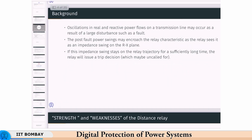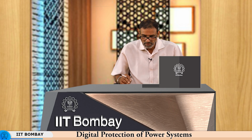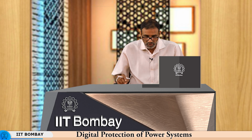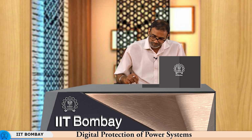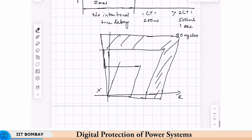Okay. So, what events affect distance relays? After an event like a fault or throw off of a large load, there may be some oscillations that result, which are known as power swings. Now, we saw in the video last time how on the RX plane, if your normal load impedance is outside of your relay characteristic, it will stay outside. During power swings, this starts oscillating here.